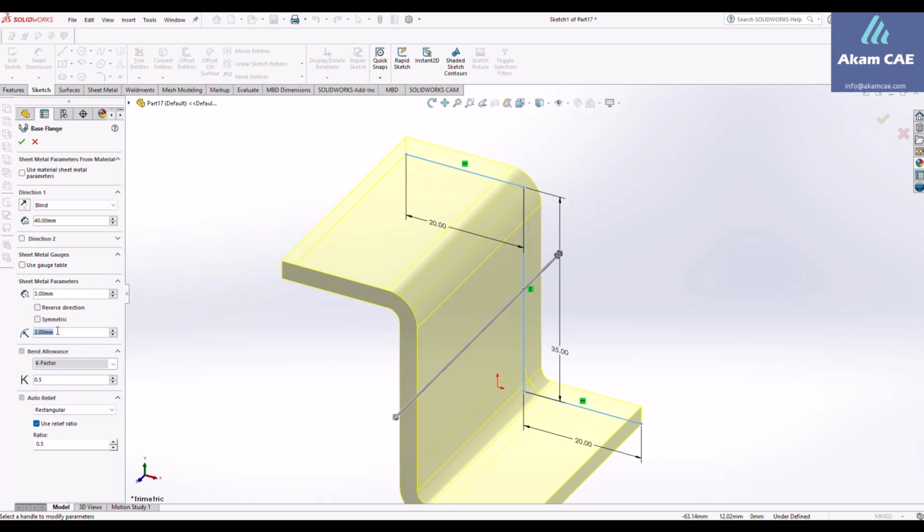And the most important thing here is the bend radius you want to choose. It depends on the function, and as a designer, you need to choose the right bend radius for your project. For example, sometimes you need a sharp bend, like a 1, or if you need a smoother surface, you can increase it, for example, to 12.5. You can also ask the fabricator what tools they have, and based on the tools they have, you design the sheet metal. Here, I just put it as a 1.